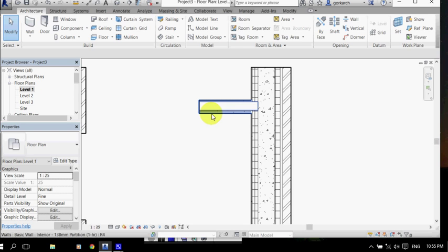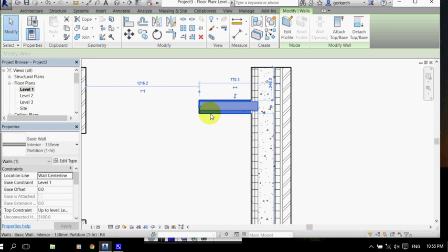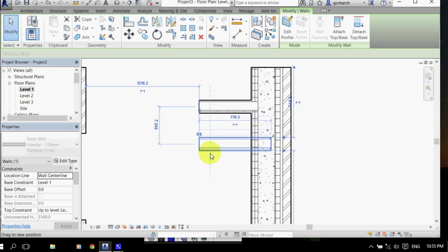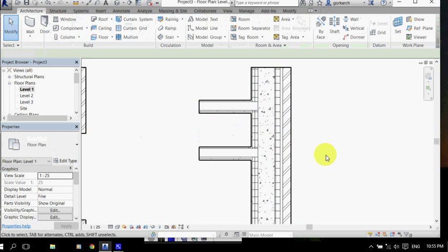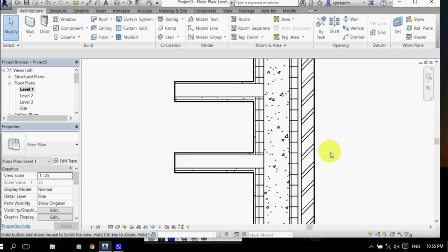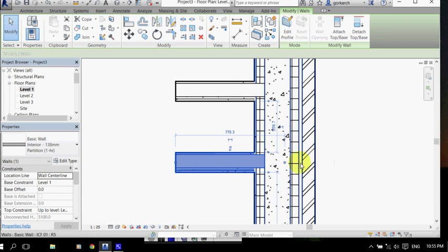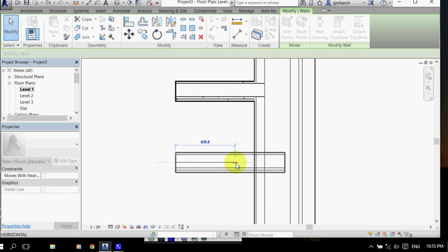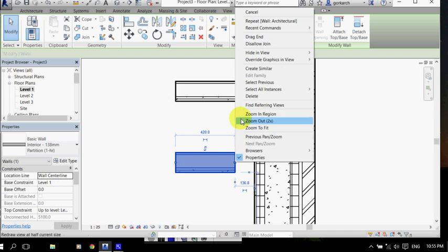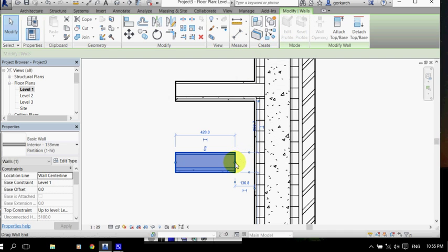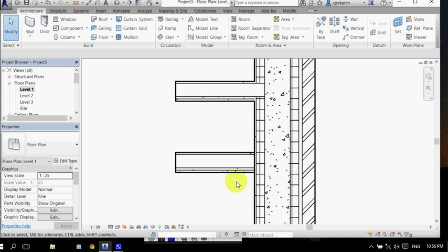Make another copy of it, so I'm selecting it, I'm pressing and holding Control, and I'm dragging this wall. So I have 2 elements like this. Very often this is not what I want to see on working drawings. I'd like to have a condition like this. Right click, disallow joint, bring it back. Because I'd like to run my fire rated drywall continuously, and the first stud is actually applied on the face of the drywall. It happens all the time, and that's not reflecting this particular condition.